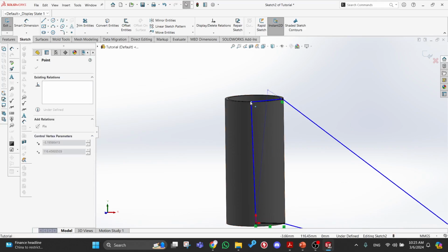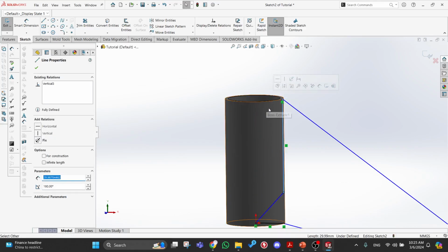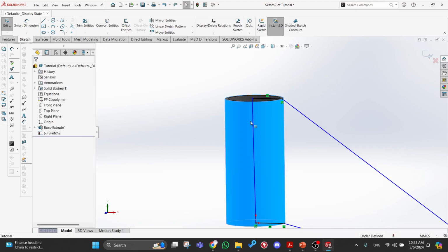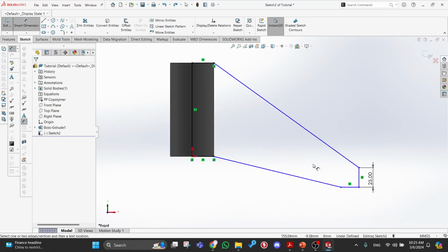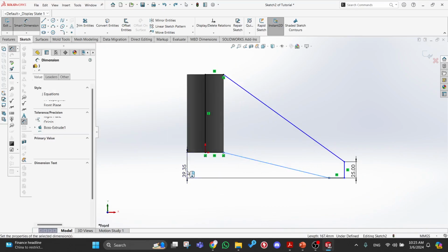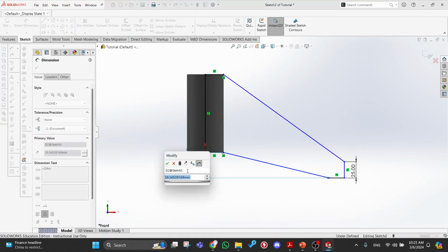Halfway. Make this not vertical. Horizontal, then this vertical. Right. So you have something similar to this. The height of this does not really matter for this context because we are not actually injection molding it, but you should have a certain amount of height, because when there's a force applied at the bottom here, it is going to push your starting point outwards, and so it's going to be displaced, so you need a certain amount of height.